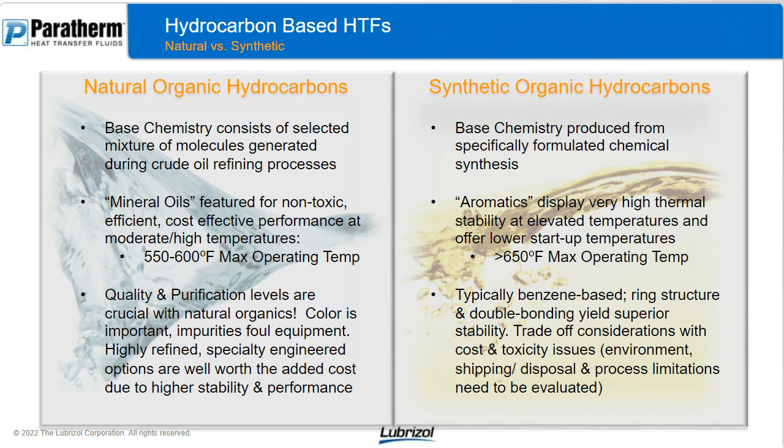Really key point about natural organics, quality and purification are critical. Color is really important. So when selecting a fluid, sometimes it's as simple as looking at something that is just the color or the physical appearance can be a really good initial indicator if you're using or respecting the right product or on the right track. So highly refined, specialized, engineered products are well worth the added cost because they're still probably within your budget, and the dividends that they're going to pay down the road are going to be really high. They're going to have higher stability and better performance.